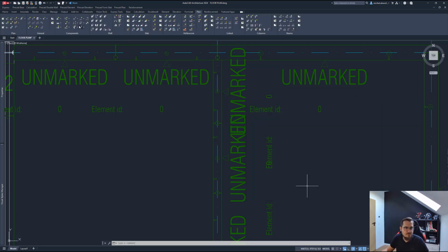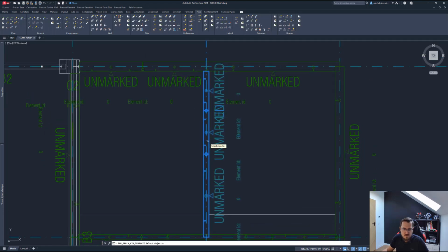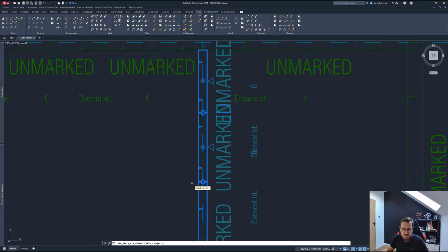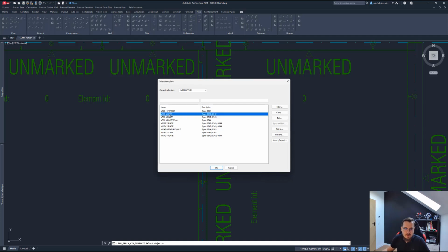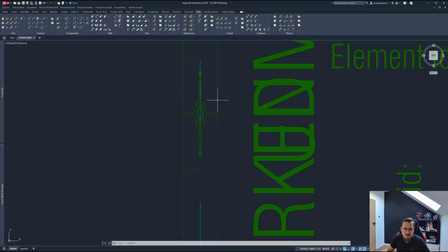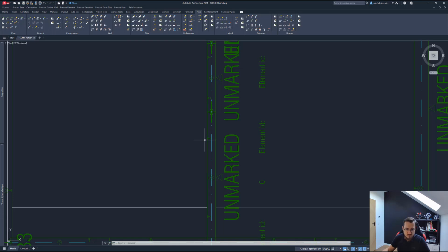And now what I'll do is I'll apply that template. So I will select objects. So those 2 walls, since I have those two types of splits here, and I'll just accept that. Right, and specify which template to use. I want this one. And as you can see, the program automatically created the connections between those two walls.